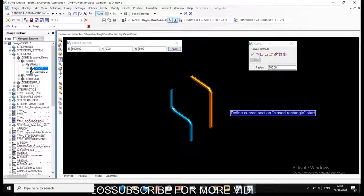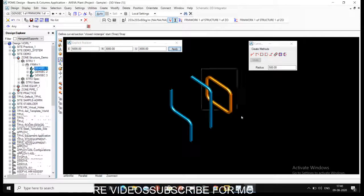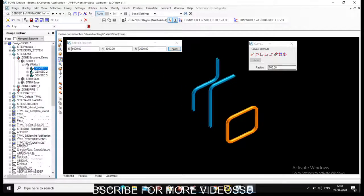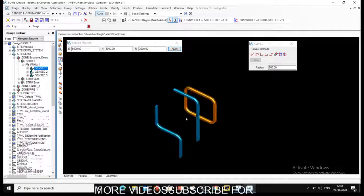Then you want to give height for the rectangle, so I will go up, say, 3000. Apply. That is my height, and then you need to give width. So width will be in north, let us say 3000. I am making a square here, and then you can say apply, and a rectangular closed section will be created with the radius of 500 on each section. Okay, so this is the closed curved section.